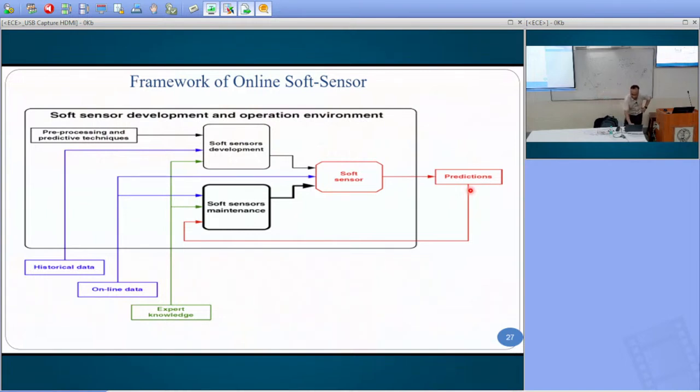There are multiple strategies of model prediction where you have a soft sensor that is predicting. You take the prediction value, and the critical variable is available every 6 hours. You take the sample, take the error between the prediction and your lab sample, and see whether the error is growing or zero. If the error is growing, the model is performing poorly, and then you need to make some corrections.